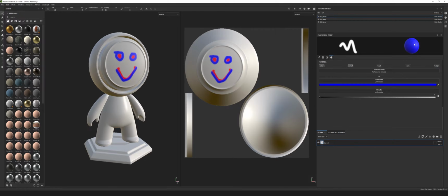Now there is a little preview window, and you can see what that value actually means in the preview and what it does. It is changing the so-called index of reflection, the IOR, and the behavior of how this shader or material is going to behave. 0 means it's not metallic, and 1 means it's fully metallic.